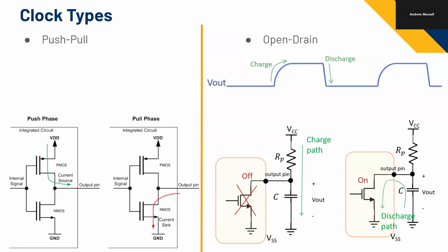And then on this output pin, you can imagine there's a capacitor here, because this device is going to have some capacitance. Then you're going to have the trace going out across the board, and there's a ground plane below that trace, right? So there's some capacitance between that. And then when I get to my load device, it probably has some MOSFET on the input, and I'm going to have a gate source capacitance.